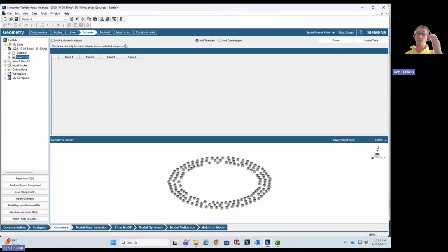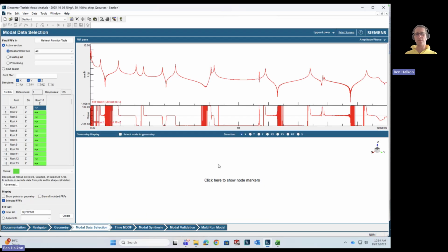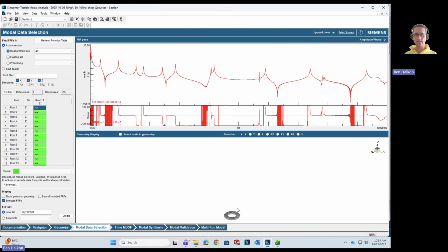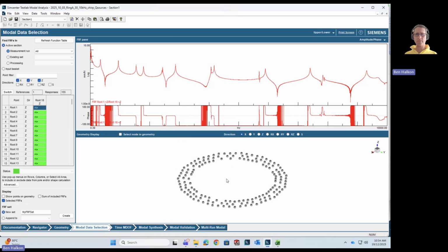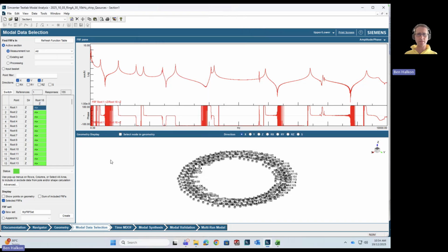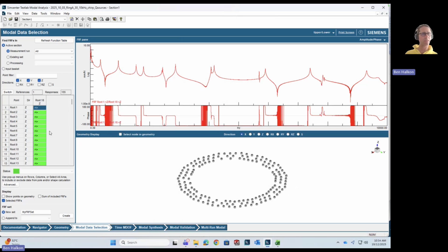We'll have to live without the surfaces for the sake of completing this video, otherwise I could spend a lot of time trying to debug what's happening. At least now we've got some geometry that will be associated with these FRFs. Unfortunately, unless you turn on the markers here, because the surfaces are missing, we don't get to see anything. And those are those points and the names, if I want to include the names. But as I've said before, it gets a bit messy.